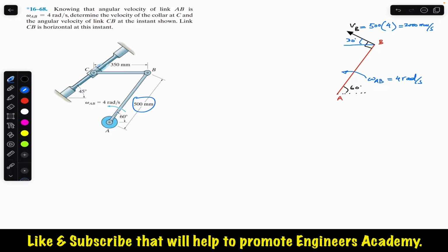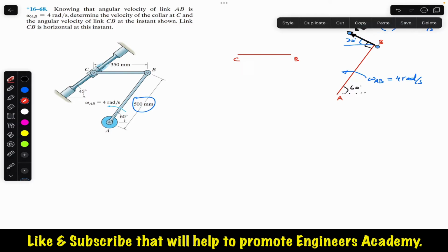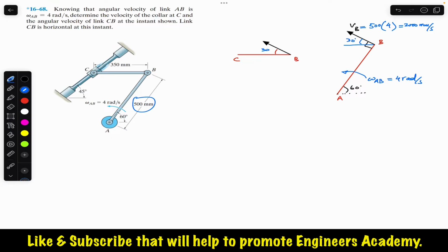Similarly, we can draw link BC. So this will be the link BC here, with this point B and point C. We will have that same VB velocity at point B. So let's duplicate this, and we will have that same velocity VB. It will have that same angle of 30 degrees. This is that same VB, which has a magnitude of 2000 mm per second.